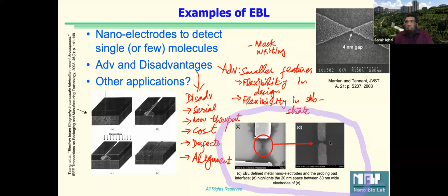And this is gold. There are two electrodes of gold coming, and then there is a break in between, and that's the sensing part. You see my arrows? The middle one, where I'm putting a thicker arrow, is the sensing part where, if you get some very small molecules, think about toxic agents or virus, you can get one virus to sit there and you can see the conductivity change through the electrodes.